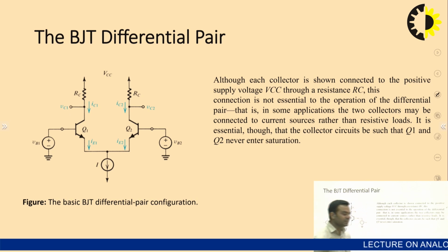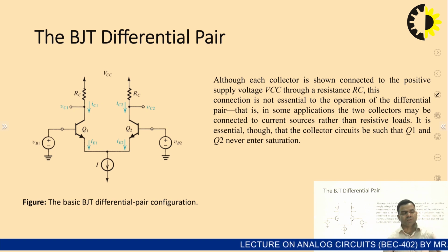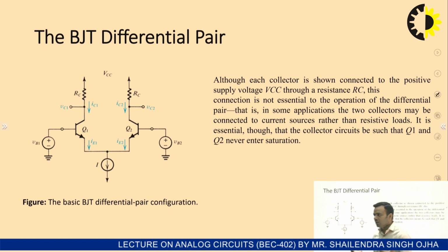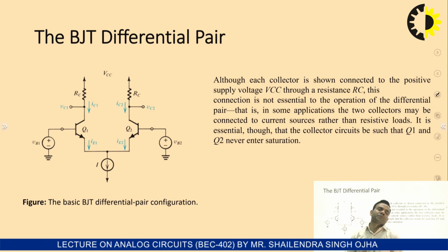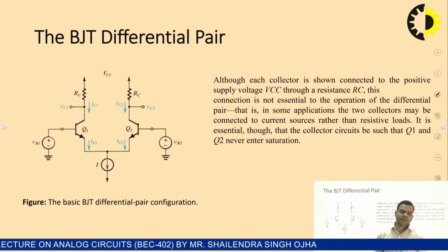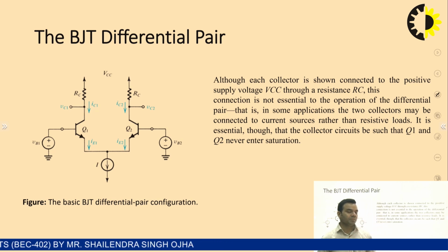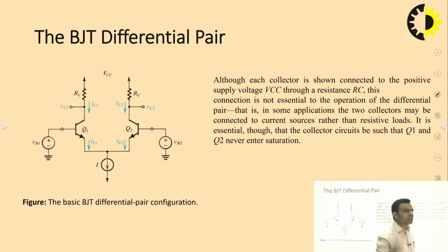Another difference: you can recall the basic current mirror circuit, and circuits with improved performance like the Wilson current mirror and Widlar current mirror circuits. All of them provide output current and you are not giving any input signal. Our purpose is to get constant output current from current mirror circuits, and in this case